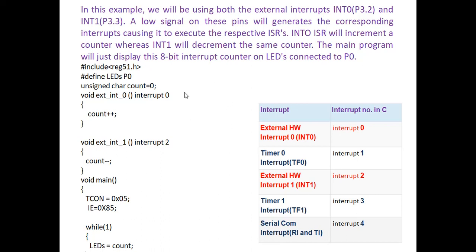So don't waste it unnecessarily by choosing data types like unsigned int and signed int. The better, regular practice for 8051 is to use unsigned char. That is very important to conserve memory space.